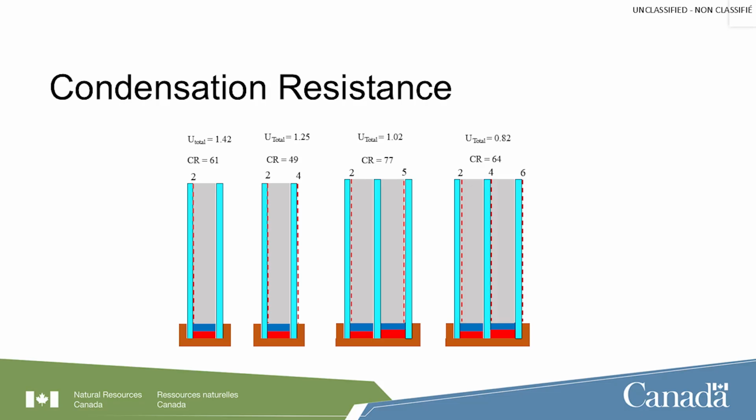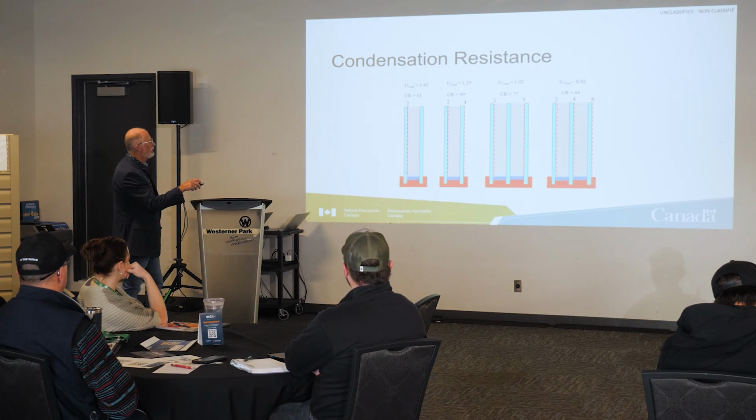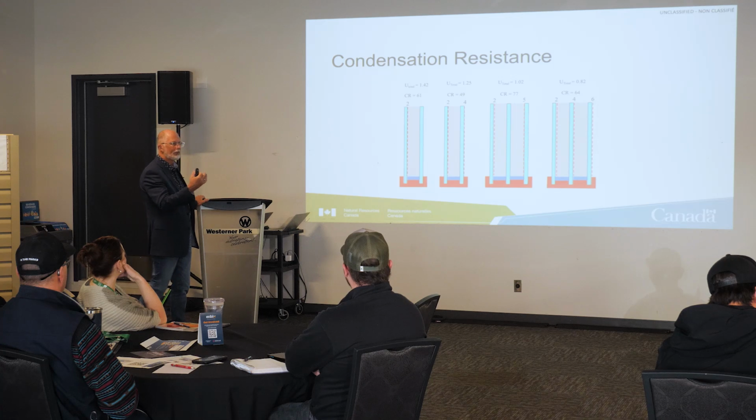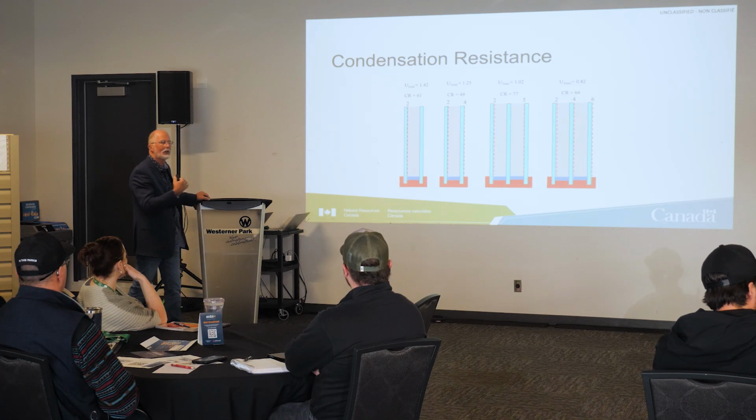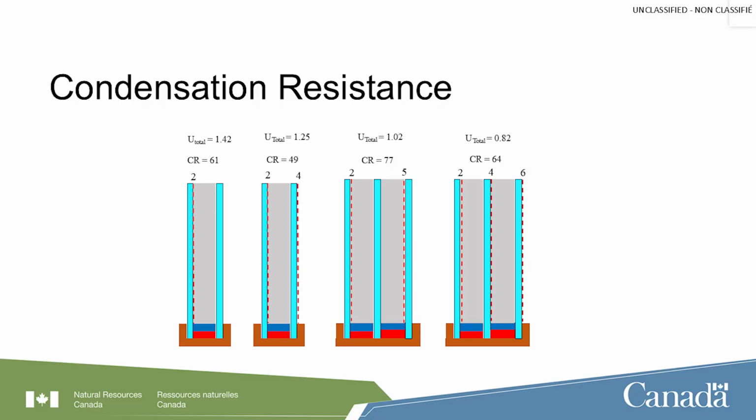What does this coating on number 6 do? Keep the heat in the room. Yeah. So it's reflecting heat back in. So it's reducing the ability to keep this warm because of a high emissivity versus a low emissivity. One's going to absorb more energy and one's going to reflect more energy. So if I look at this one, there's no coating here. So the heat from the house is going to absorb into this piece of glass. Whereas this one, it's going to reflect the heat from the house.